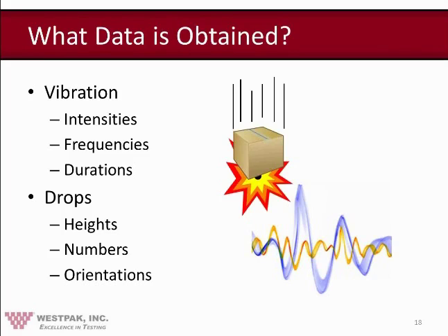History has told us that the weight of the package system, and to some extent the package size, will have a large influence on the drop height that the package might experience. The reason for this is that impacts during shipment are a people phenomenon. That's important to remember. People cause impacts. People throw packages that result in impacts. That's why most quantification of the drop height environment involves the weight of the package system being studied.